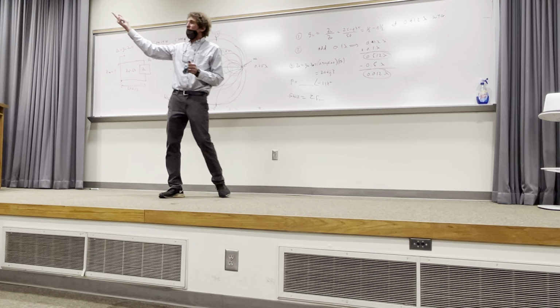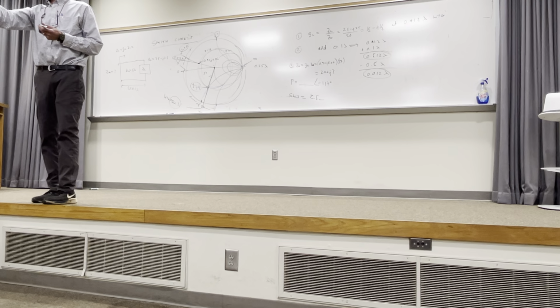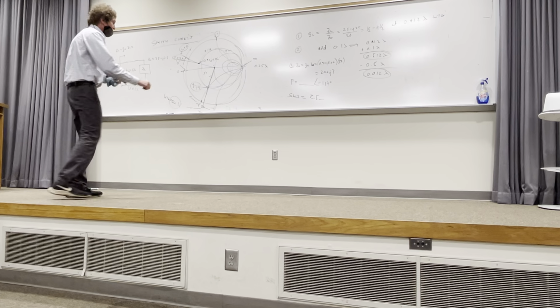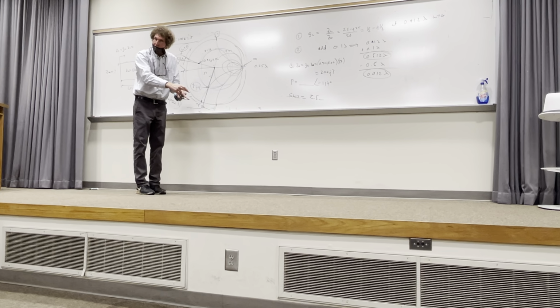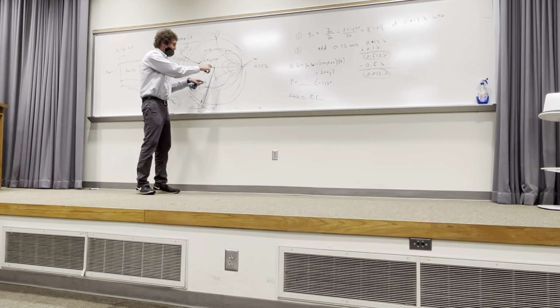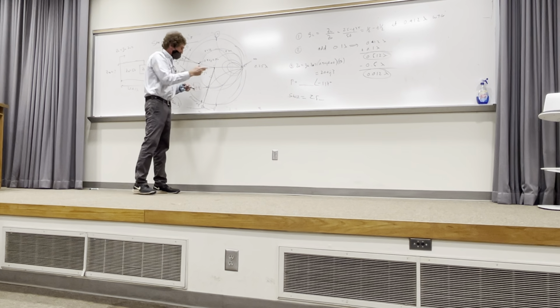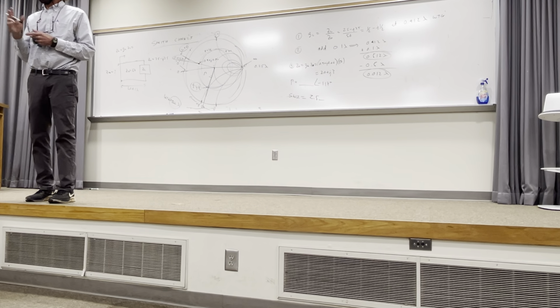You guys get anything over there? Do you have the ability to do this or measure? You know what I'm talking about at the bottom of the Smith chart? You can get the magnitude, right? You take the length of this from here to here, and you go at the bottom, and it'll have reflection coefficient. The longer this is, the larger the reflection coefficient. It goes all the way to 1, right? When it's this big. But ours is going to be, I forgot exactly. If you take a look in there, it'll be somewhere around 0.5-ish.